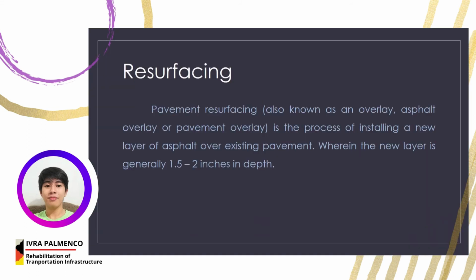One of the methods of rehabilitation is resurfacing. Pavement resurfacing, also known as an asphalt overlay or pavement overlay, is the process of installing a new layer of asphalt over existing pavement, wherein the new layer is generally 1.5 to 2 inches in depth.